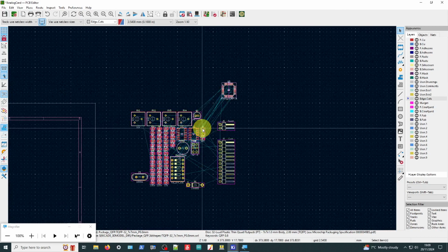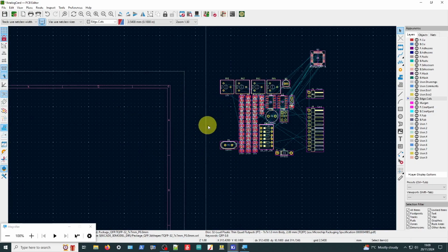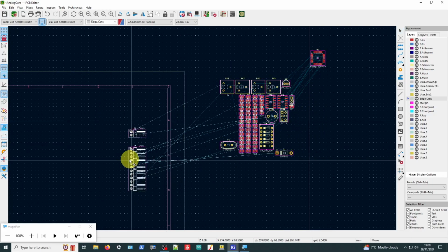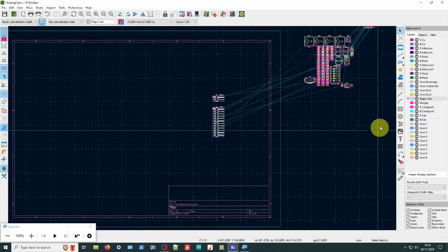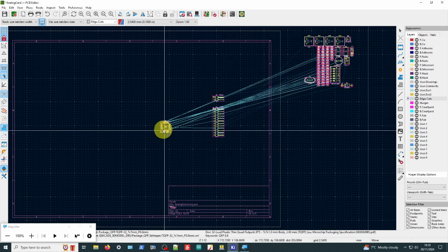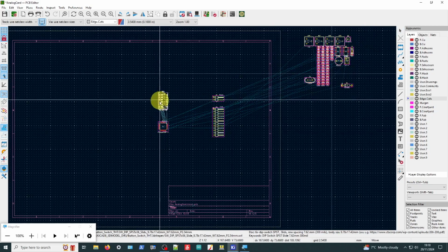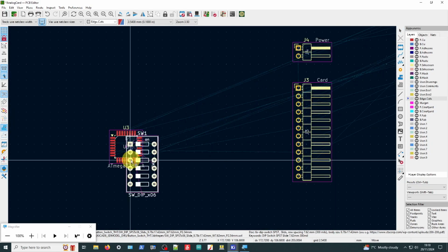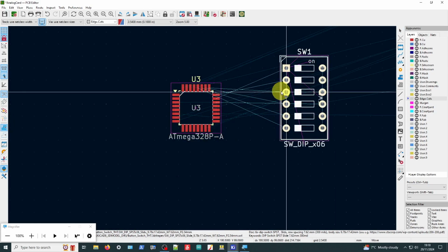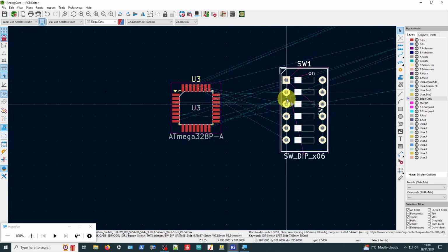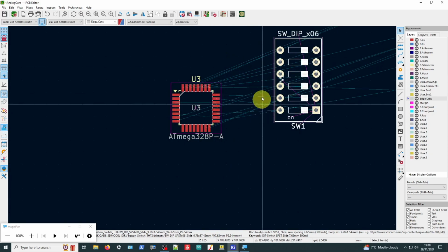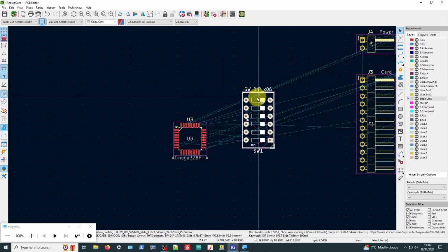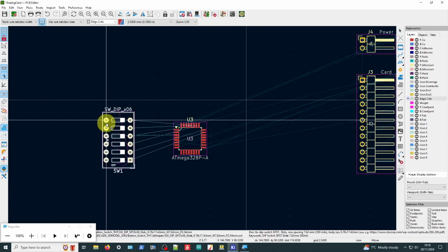What I'm going to do is spend a bit of time, move these components around where I want them, and you can drag them around to the board design. It needs to go in here, and then take the components one at a time, probably put the, I'm just guessing here, and the switching. Now what you can do is look at the rat lines and go, okay, maybe I want to rotate that the other way, and just try and avoid too much crossing. Sometimes it's a bit difficult to say. Just get a feel for it.